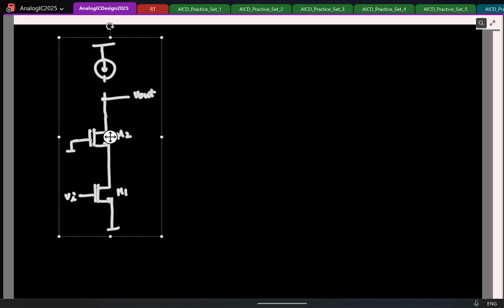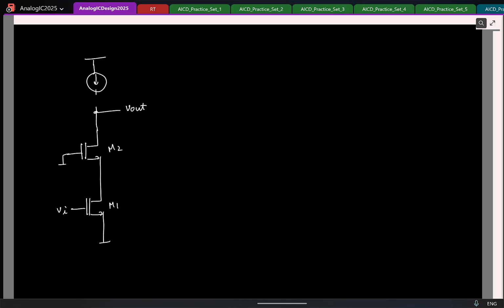So let's quickly check the poles and zeros here. Okay. So let's start with poles. Again, for pole locations the input doesn't matter, so I'll make the input 0. So again, let's try to lump all the capacitors. So let us say at the output I again have a large capacitor dominated by the load CL. So I have another capacitor here, C1, from this node to ground. There will be no other capacitor. All the capacitors you can lump into these.